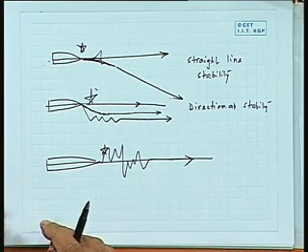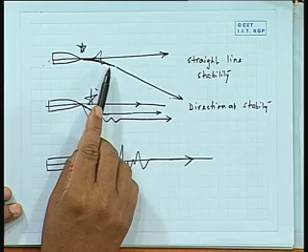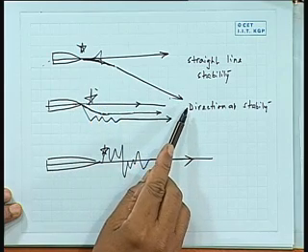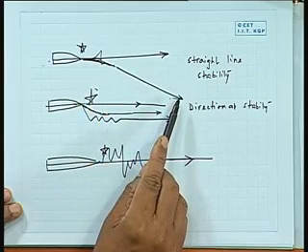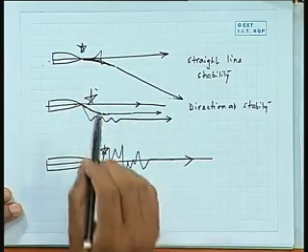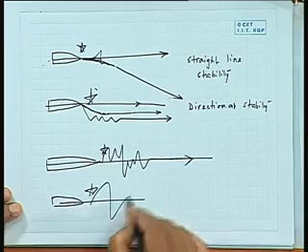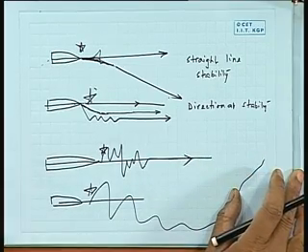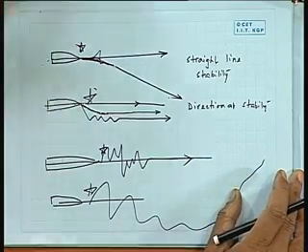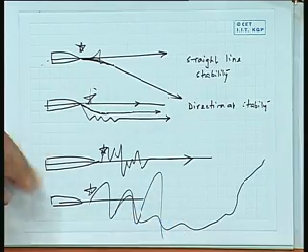So, in other words, in case 1 the disturbance when given has caused the ship to go along a straight line after you have removed it. Okay. So, it is having a straight line stability. In all these cases, it is possible that when you give a disturbance, it simply goes to some other direction, then it is an unstable ship. Supposing a ship cannot be controlled, there is a disturbance, it simply introduces some force, and in fact what will happen, it actually goes larger and larger, then it is an unstable ship.